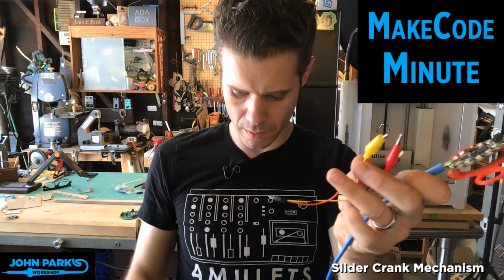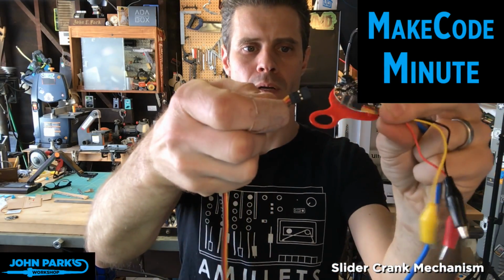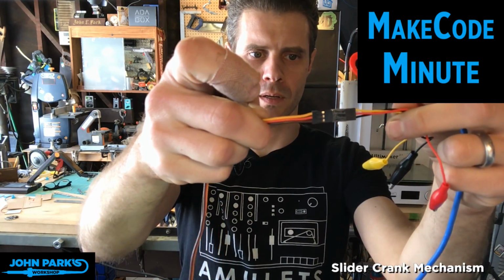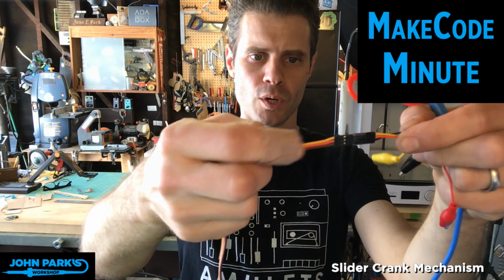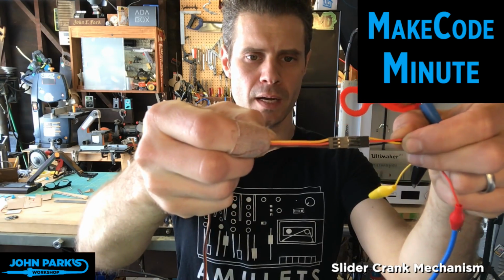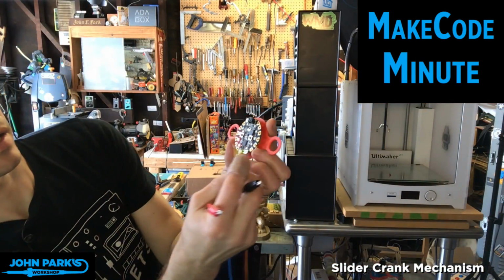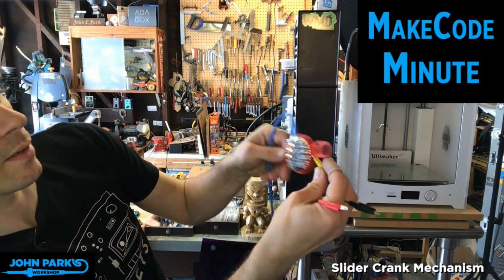If I plug those in to the servo, I've got those lined up for signal, power, and ground. For some reason these servos use brown for ground, but that is ground, and this orange for power, and then yellow is the signal. So I kind of match them with my alligator clips. And now I'm going to connect, let me put this somewhere where you can see it, to A1, oh, I'm upside down.